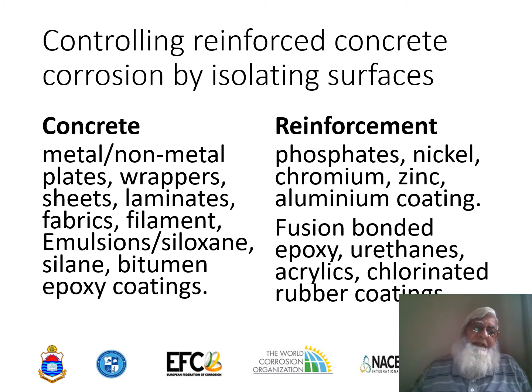But the most useful and faster application for isolating the concrete surface from the environment is the application of emulsions or coatings like siloxane coatings, silane coatings, and bitumen epoxy coatings. Bitumen epoxy coatings are generally not so beautiful. They're black in color and normally applied at the foundation level where they're not visible to the public eyes.